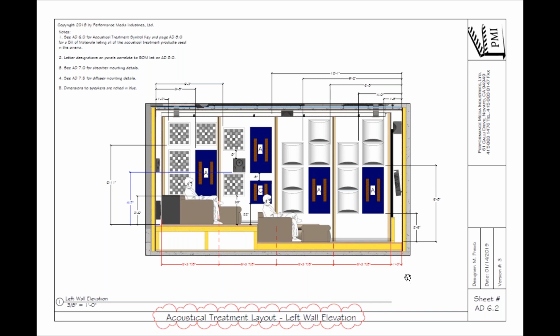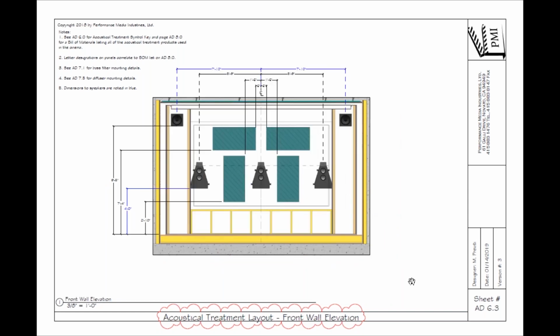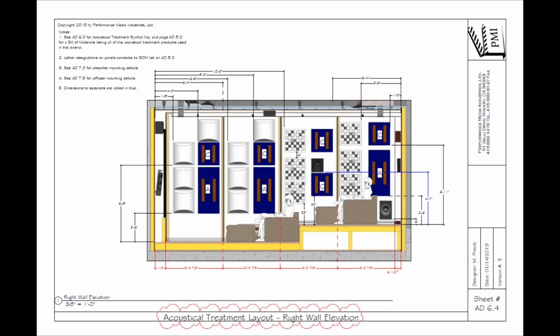So overall, the left wall has more or less the same amount of absorbers and diffusers as the right wall, but they're laid out slightly differently, so that when you're in the middle of the room, the pattern that comes off the left wall is slightly different than the pattern on the right wall. If it was identical, you would misinterpret the wall reflections as an intentional sound coming from the speakers. When your brain hears a correlated sound coming from the left and from the right, it thinks that's an intentional sound. There's a lot of science, a lot of research on psychoacoustics.